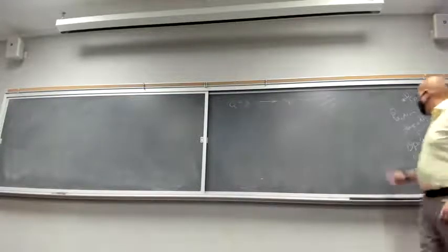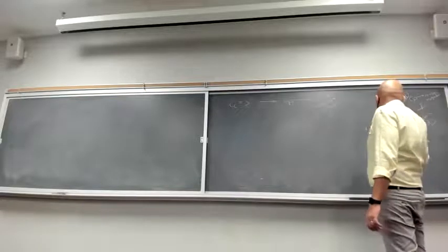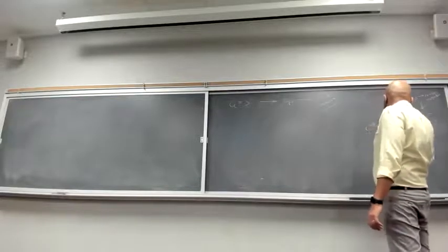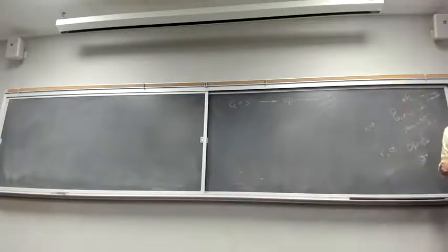Then for first part, yeah, the most negative CP. But for second part, I wanted you to find the location of the stagnation points, so essentially R and theta, and location of where P equals P infinity.